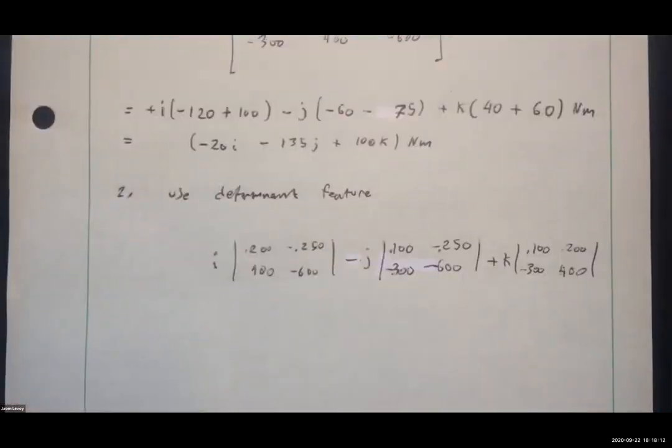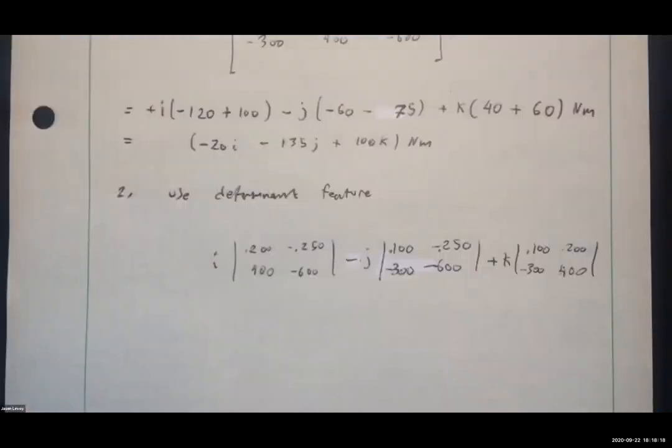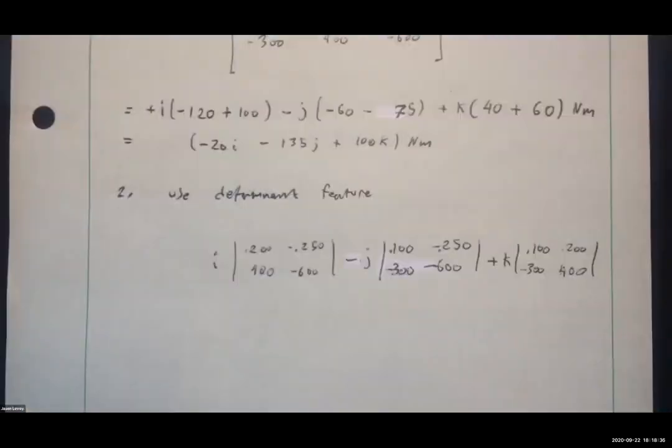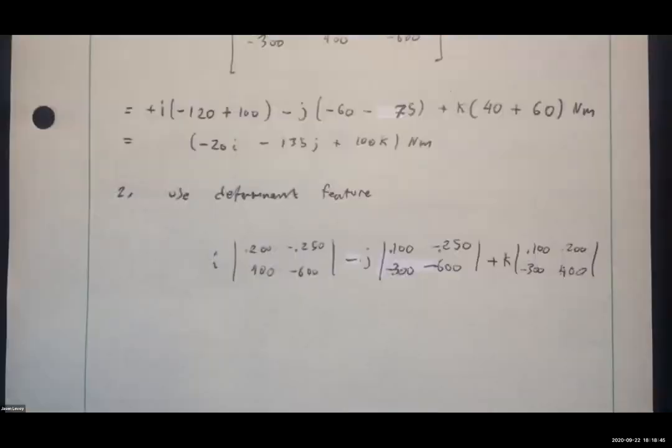Yes, so the calculator can do determinants. It's happy doing determinants, but it will not do a determinant with variables in it. So putting in an IJK, which aren't variables but are letters, it can't do it. The only way the calculator could do a determinant is if you break it out the way you did and do a 2x2 determinant. Because in the end, this force is creating a moment that has an X, Y, and Z component. It's like a top that's not spinning completely vertical. It's spinning to the side, and you're getting an X, Y, and Z component of it.